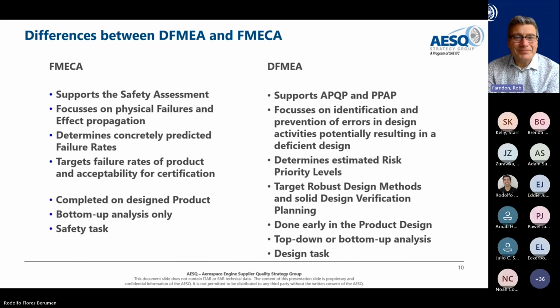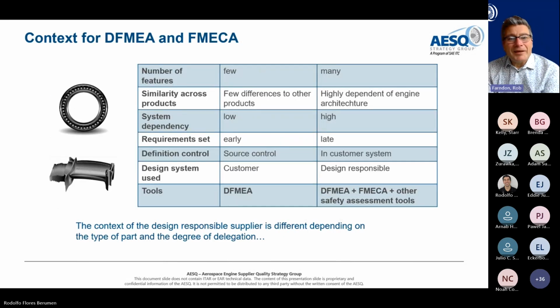Okay, thank you. Could we have the next slide, please? Okay, so whether or not you do a DFMEA or a FMECA or both is determined, at least in part, by the context in which you're operating. If you've got a design with very many features, you are likely to need a FMECA as well as a DFMEA.